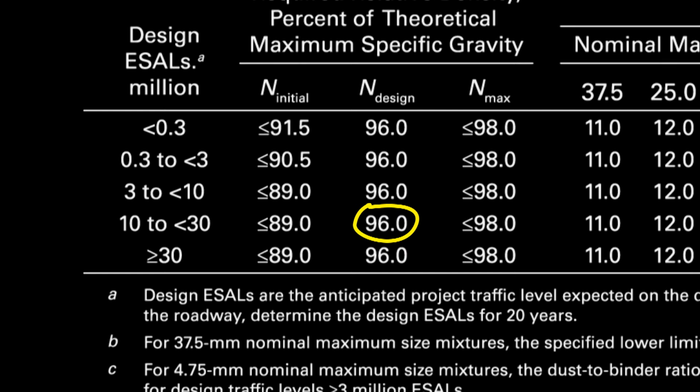Our overall target in SuperPave mix design is to achieve 4% air voids at our design compaction level. If our air void content is above 4%, our mixture will be dry and susceptible to cracking. If our air void content is below 4%, the mixture will be too soupy and soft and therefore susceptible to rutting. Therefore, it is critical that we achieve 4% air voids in our asphalt mixture. Our estimated air void content at our corrected binder content was 4% since that was our design objective. Therefore, we meet this requirement of SuperPave.